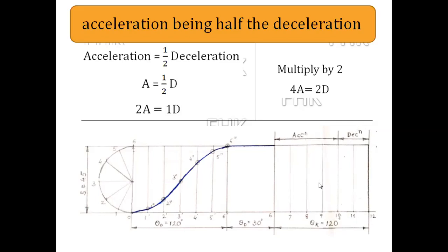So that mid line I divided into 6 equal parts, but that case is not happening in this situation. 4 parts I am giving for acceleration, and 2 parts I am giving for deceleration, and from that I will draw the vertical line, which is the 10 line.